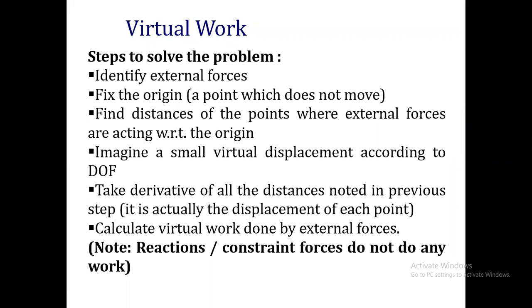So first of all, we identify the various external forces acting, and in that process we take all the external loading into account. That may be point load, distributed load, point moments, a force due to gravitation, a force due to tension in a string, as well as a spring force or any other external loading.